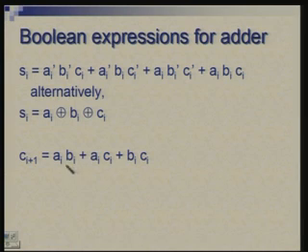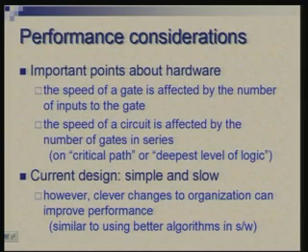So, you will have one level of ANDing, a series of AND gates and then an OR gate. I am ignoring inverters, these complements, for the moment. They will also have delay which has to be accounted for, but it will be smaller as compared to AND and OR. So, this circuit can compute the sum and carry in 2d time.